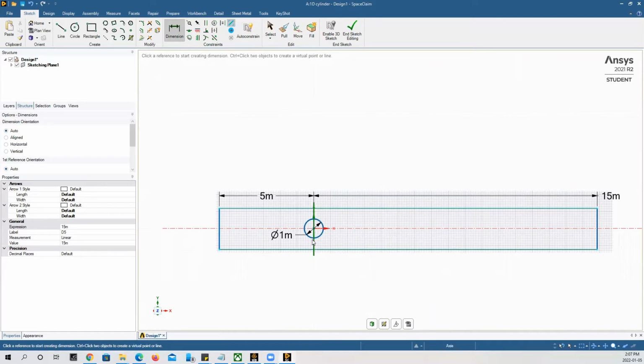So before the cylinder, we're going to have a uniform flow because we're specifying the inlet velocity of the flow, and nothing is in the way of the fluid. So it's going to be a uniform flow. Whereas we are interested to see what's going to happen after it interacts with this body here that is in the middle of the flow. So this is why we make the outlet length longer, in order to see how the fluid will behave after its interaction with the cylinder here.